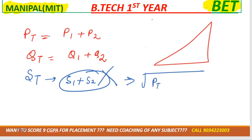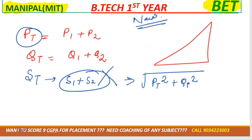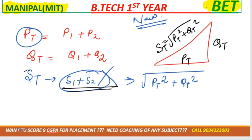So for this case जो ये PT आया है, total active power का square plus reactive power का square, because this is the new power triangle you need to make. For the new power triangle, this is the total active power, total reactive power, and total apparent power is always PT ka square plus QT ka square. Never do this S1 plus S2, because 95% of the students do this mistake, and this is a common mistake.